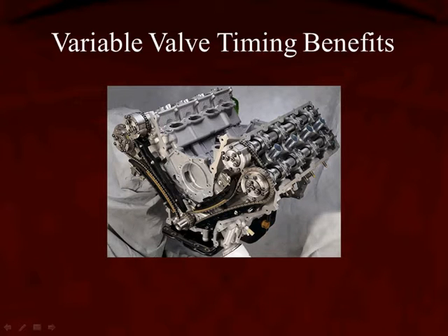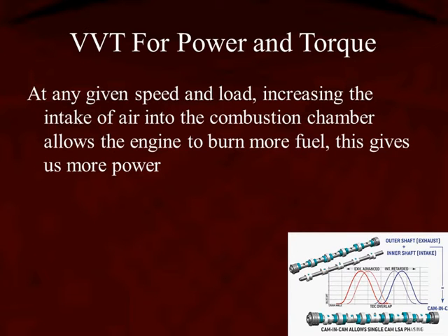Manufacturers have gone to variable valve timing or variable cam timing, or one more for you, independent cam timing, timing of each camshaft, intake and exhaust, for different benefits. And mostly it's power, performance that the customer wants, and reduced emissions with increased fuel economy. We also get power and torque improvements when we use the independent variable cam timing.